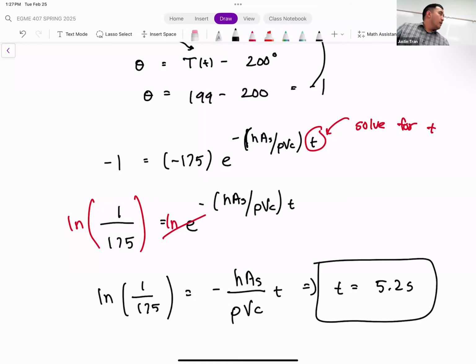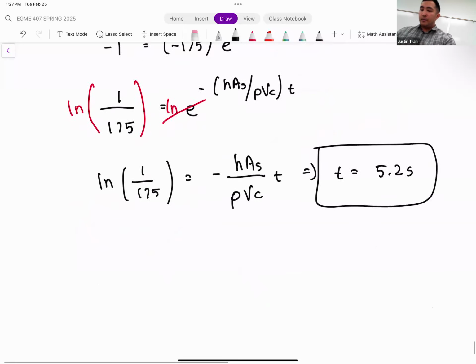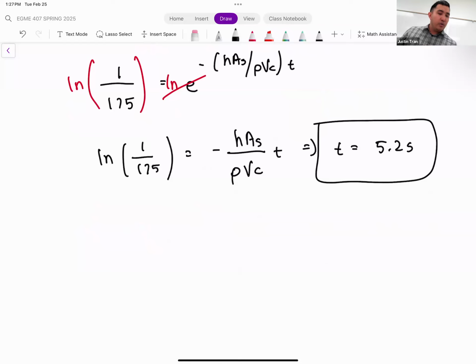So that's, I would say, the simple form for lump capacitance, where we only consider just convection. But really, for a more general situation, you can have different sources of heating as well. You can have an object that is producing heat, or an object that's getting heat from another source, like a heat flux, or it might be getting radiation as well. So we can modify our lump capacitance equation to account for these more general situations. This is the last topic that we'll cover in this section.